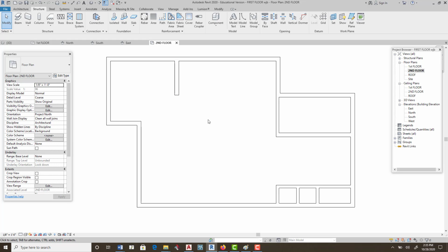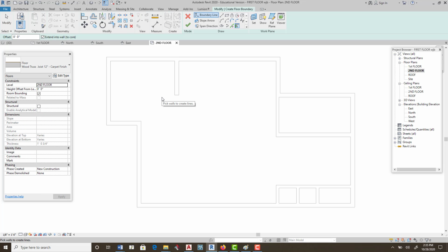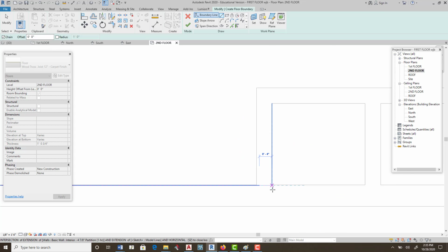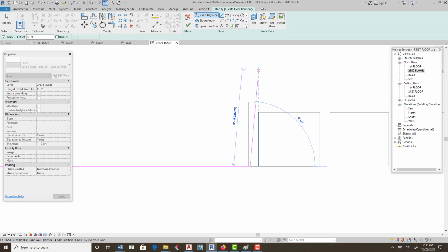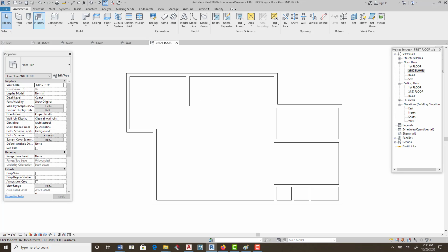Now, you're going to use the inside wall this time. So let's go to architecture, not structure. Let's go to floor, floor architectural. So now, let's put a floor in, starting here. Now you can start and stop and put different materials on there, okay? Let's see, that's not on the line there, so let me undo that, X out of there, discard it, start over. Always make sure you're doing it correctly.